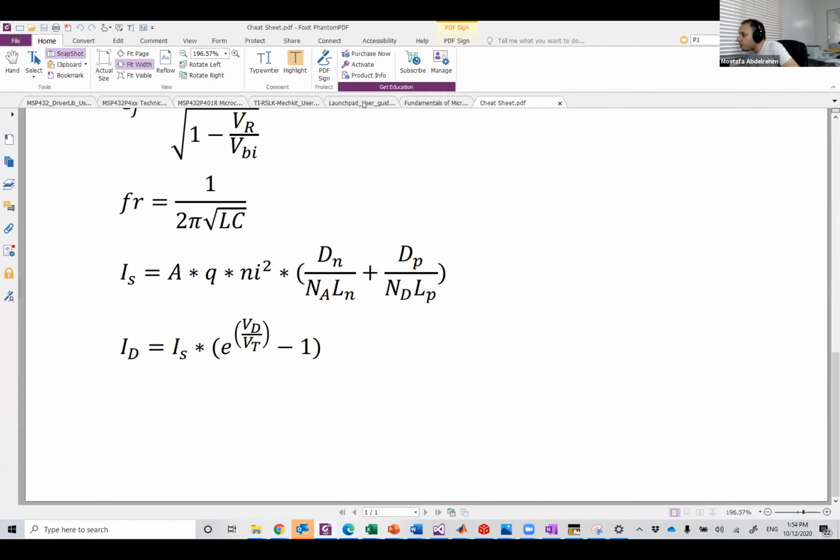Okay. So let's see how this out. Yes, I have a question for line 13. You're sending 0 to pin 0 port 1, right? Yes. Here you are sending 0 to the whole register, so all 8 bits will be zeros.